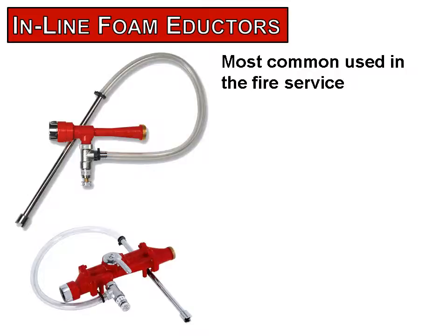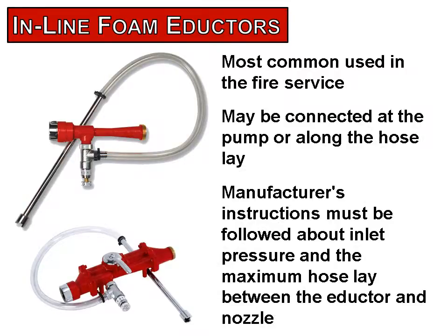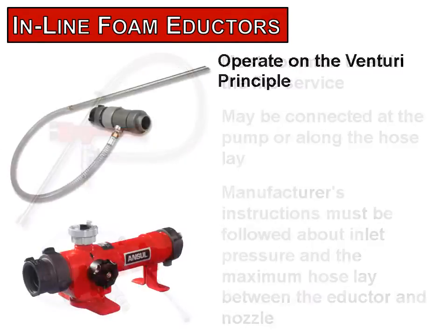Inline foam inductors, most commonly used in the fire service, may be connected to the pumps or along the hose lay. Manufacturer's instructions should be followed about inlet pressure and the maximum hose lay between the inductor and the nozzle. They operate on the Venturi principle.